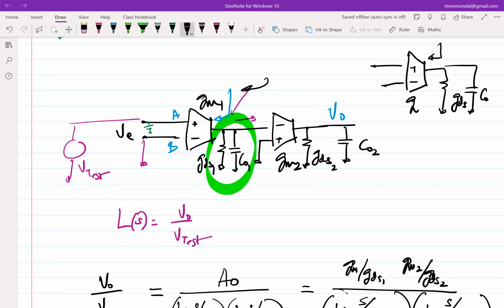Okay, so this does not mean that I can extract the GDS and throw it out. This is just a model. When you make an OTA and check the output impedance, you will never get infinite because GDS comes along with it. In simulation or in actual life, you will not be able to isolate this GDS, but in a mathematical model, you can draw anything. So this makes our life easy. That's why we do it, right? Okay, fine.